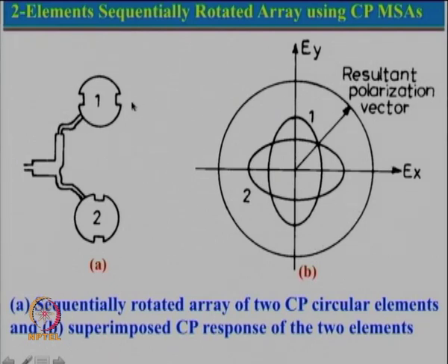Now, at higher frequency, when this is dominant, then for 1 this will be the field pattern, and for 2 this will be the field pattern. Okay, this will happen at higher frequency. So, again now if we take x square plus y square, we will get a circularly polarized component. So, that means by using this particular configuration, we can actually get a circular polarization over broad bandwidth.